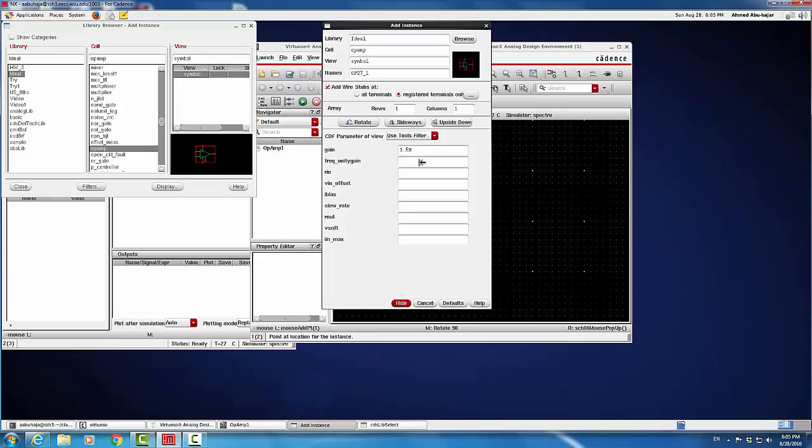The frequency, the unity gain frequency is basically gonna be 8 meg, and Rn gonna be 4 meg, and Vn offset I can use 30 micro. So U stands for micro. We're gonna say 30 U, which means 30 micro. The input bias current going to be 15 nano. The slew rate, we have it to be 8 meg, and our out going to be 70 ohms.